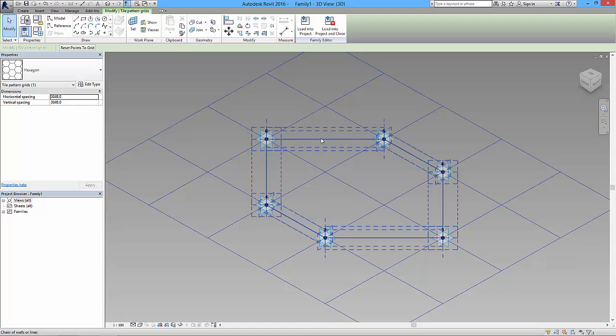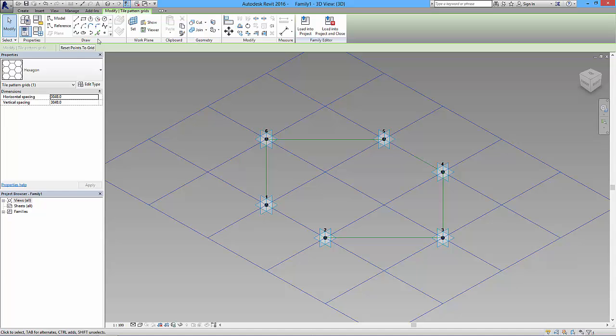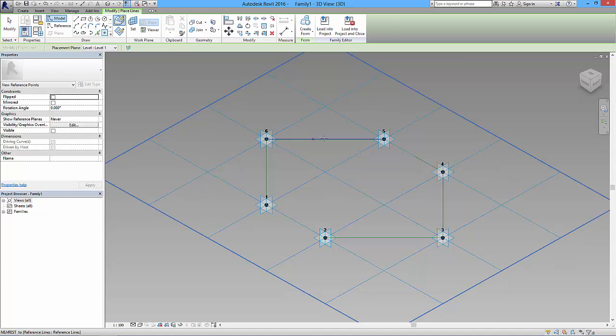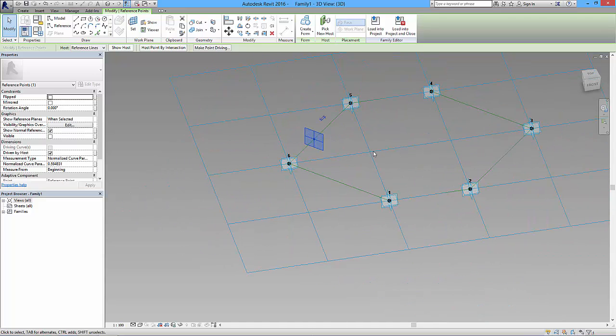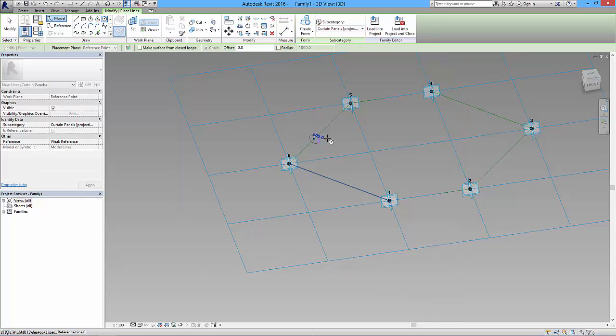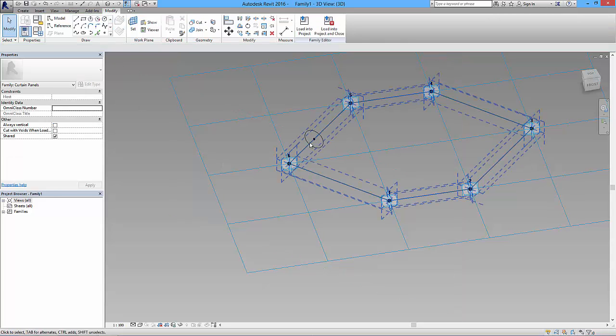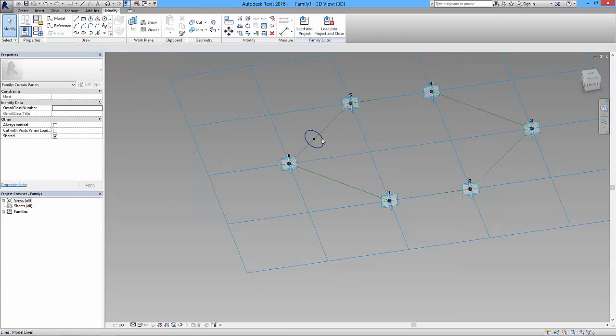So I need to create a node on this so I can use that as a reference plane. So I'll pick this thing here, so point element, and I'll click anywhere along this edge, and that's going to be fine. And then I can click on that, and this is giving me my reference plane to draw from. So a circle, and then I'll click on that reference plane and just drag it out, so it's about 400 mil. That'll be fine. I could control this by adding a parameter to it, but again, I'm not going to.